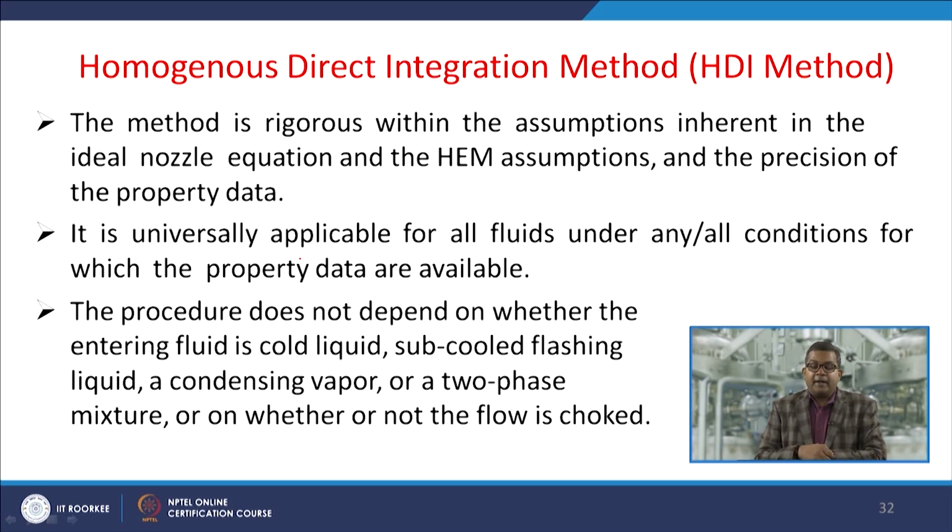This model is rigorous within the assumption inherent in the ideal nozzle equation and the HEM assumptions and the precision of the property data, which you can have from various handbooks. Now it is universally applicable for all fluids under any or all conditions for which you have the property data available. This procedure does not depend on whether the entering fluid is cold liquid, subcooled flashing liquid, or a condensing vapor, or a two phase mixture, or whether or not the flow is choked.